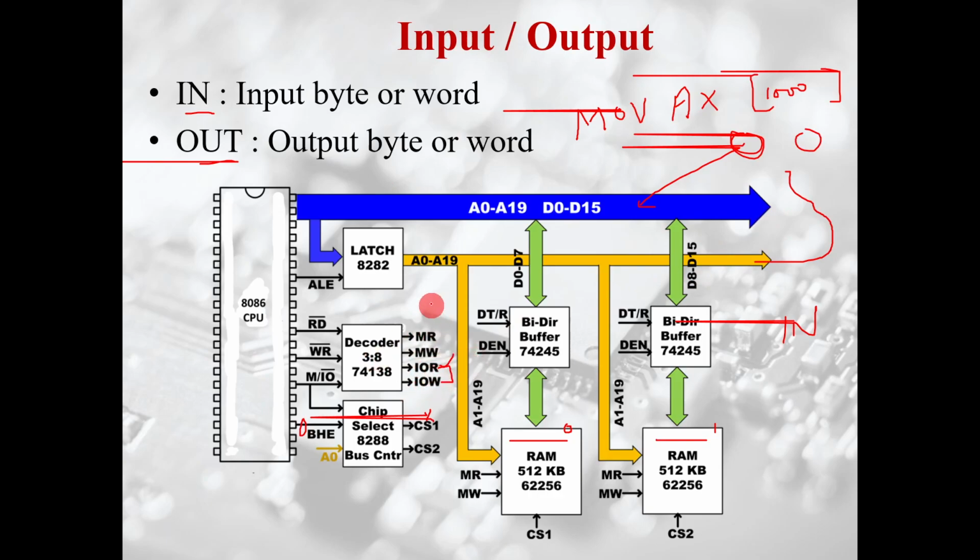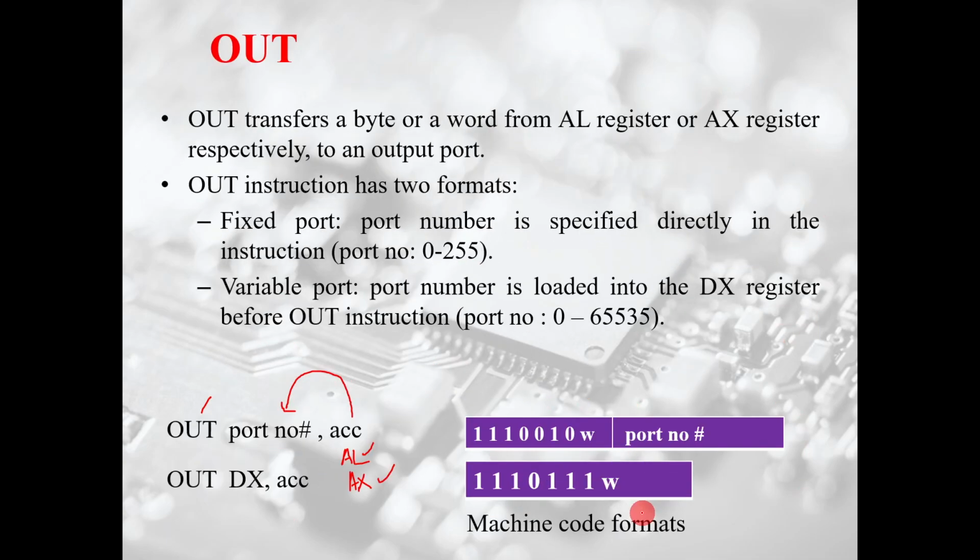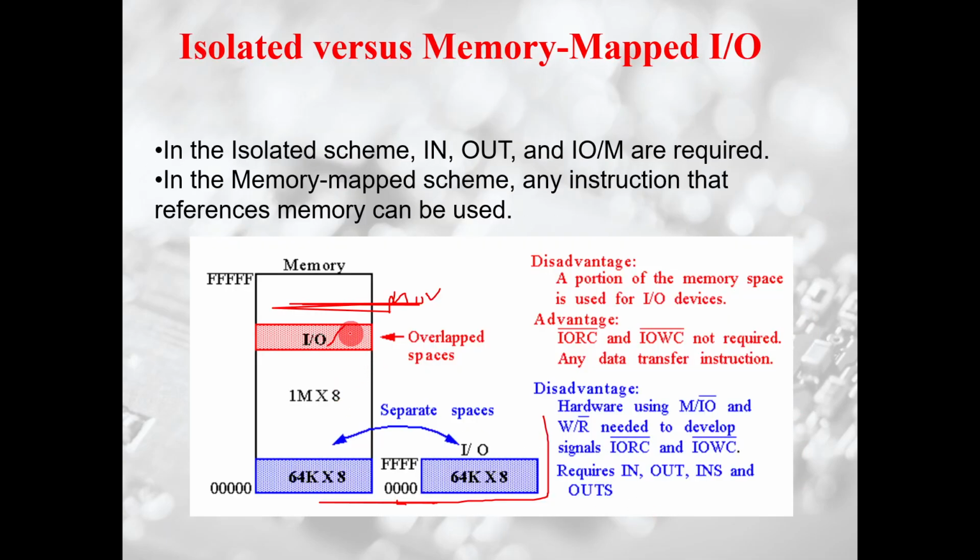You could remove this complete memory bank, use a smaller memory bank here, and connect the rest of the address lines to IO ports instead of the memory bank.